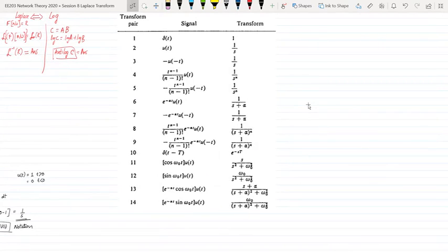And when we wanted to solve something like C is equal to A plus B, we had to go and refer to the tables, find log A, log B, add it up, and then take the anti-log to get C. Similar to that, we have a Laplace transform table. These are the various Laplace transform pairs. If my input is a step function, we solved this, right? We said that the Laplace transform is 1 by S. If the input is an exponential function, then the Laplace transform is 1 over S plus A.